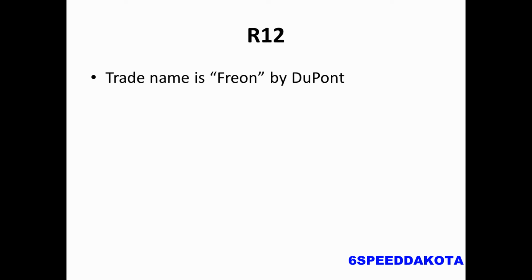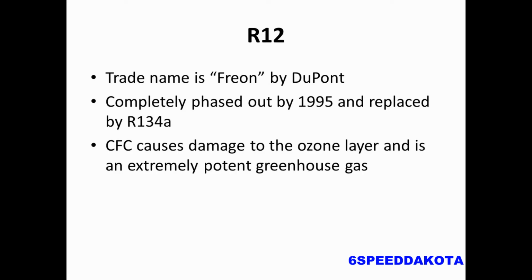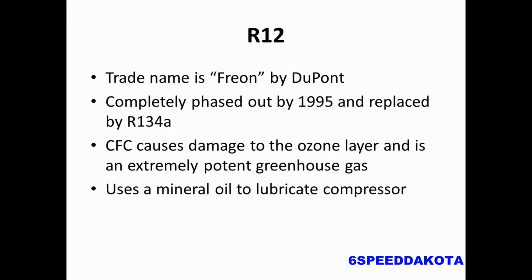So, R12. Again, trade name is known as Freon by the DuPont company, and it has been completely phased out by 1995 model year, and it has been replaced with 134A. Since it's a CFC, which stands for chlorofluorocarbon, it causes extensive damage to the ozone layer, and it is a very, very potent greenhouse gas. An R12 system uses a mineral oil to lubricate the compressor, basically like a conventional motor oil, so a non-synthetic.